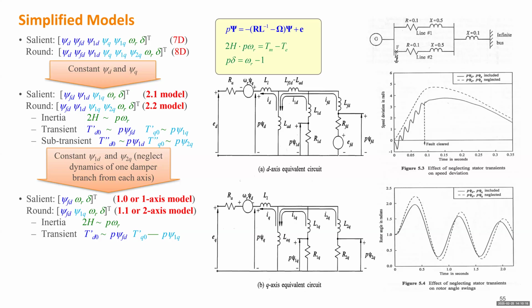If you read any paper written by control people, someone from outside of power engineering, this is the most complex model they are going to use. They are a little hesitant to use only the swing equation. If they use only the swing equation, you will say that's not good, so they add this one. They don't bother adding damper winding because that's too complex to figure out.